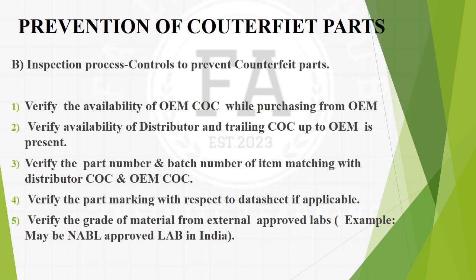And the next point is to verify the part marking with respect to the datasheet if applicable. For most electronic items like ICs and capacitors, there should be a permanent part marking on the item, so we can verify this part marking with respect to the datasheet and ensure that the product is not counterfeit.